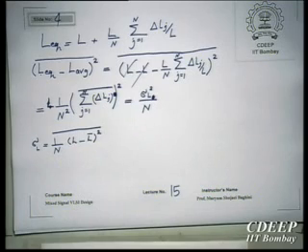So what does it mean? It means that if I have a standard deviation for L, and I increase L, in other words, I'm increasing N, right? Then I actually get less standard deviation for equivalent L. That means that the total variation in the transistor will reduce if I increase that area.